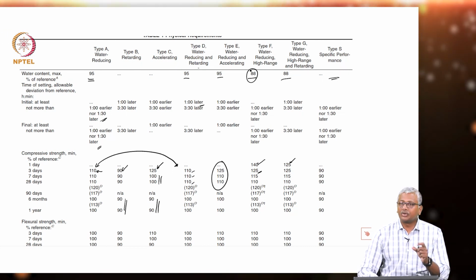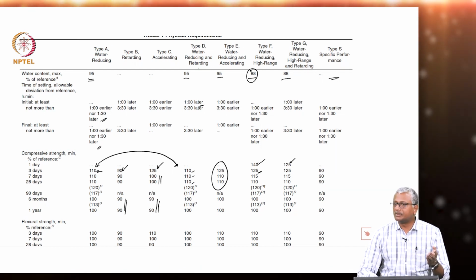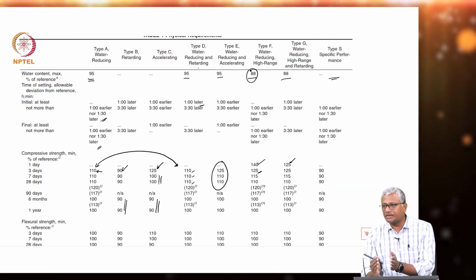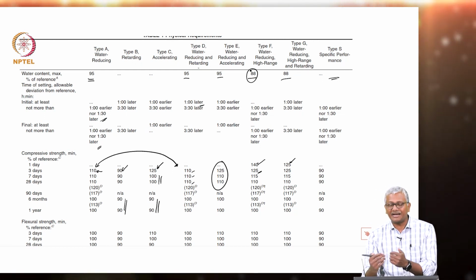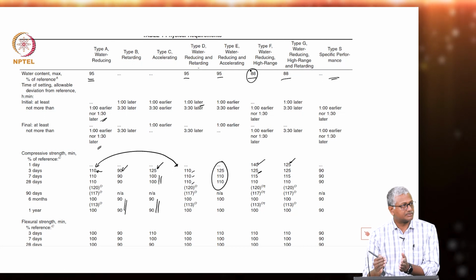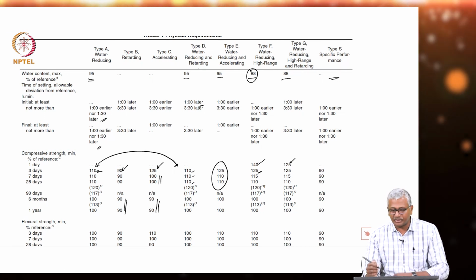Okay. So, when you try to use in a real project dosages that are not in that recommended range, there is no guarantee of the performance. So, the admixture company will guarantee the performance only in that range. Okay. So, it is very important to pay attention to that.